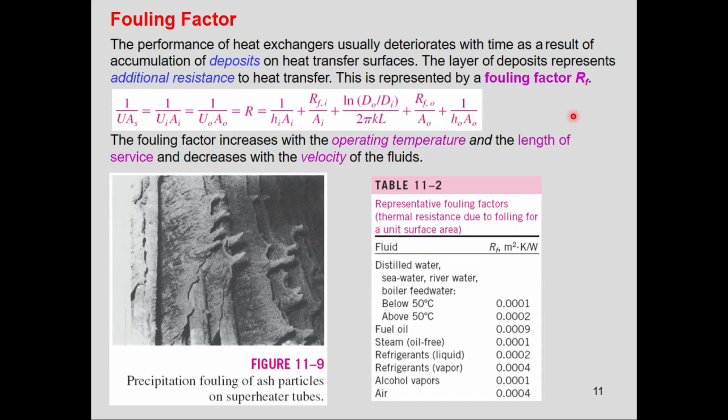This is a usual case when you boil water in a pan at your home. You sometimes see that after the boiling, the inner surface of the pan becomes somewhat white. This is due to the deposition of the salts which were present in that water. When you boil that water, the dissolved salts settle down and stick to the inner surface of the pan. So if the same phenomenon happens in heat exchangers, this accumulation grows up and ultimately adds resistance towards the heat transfer.